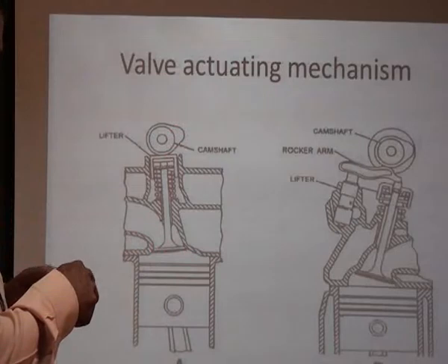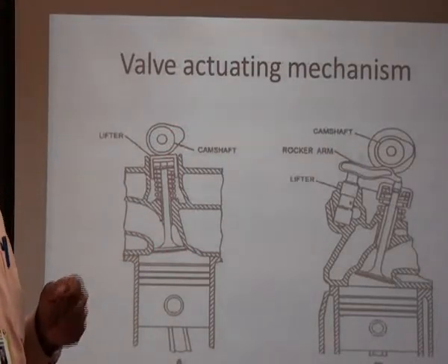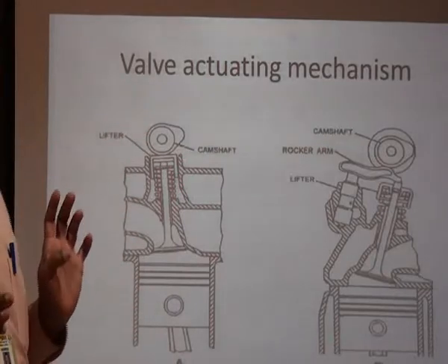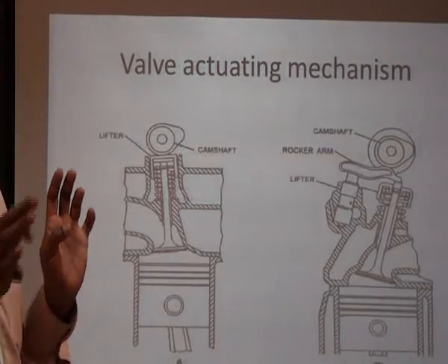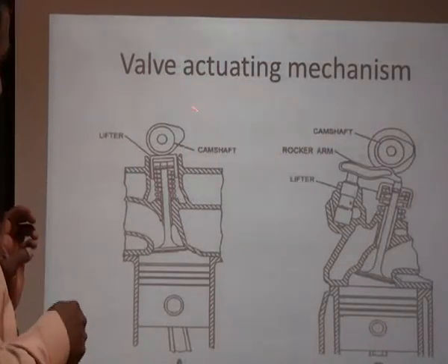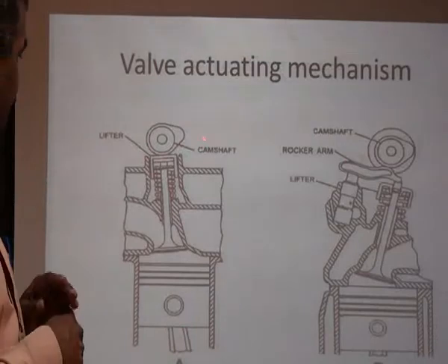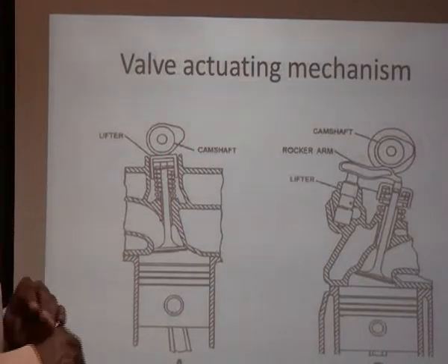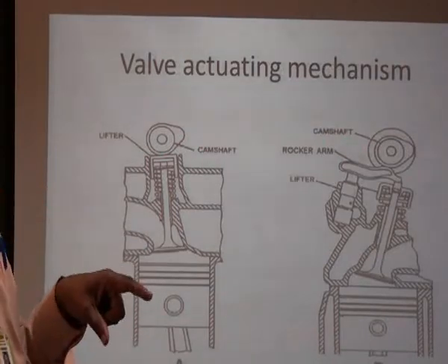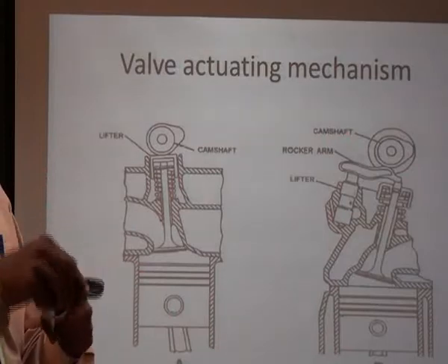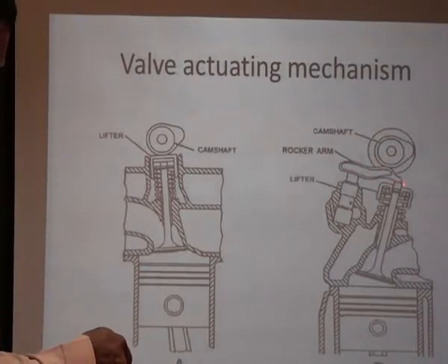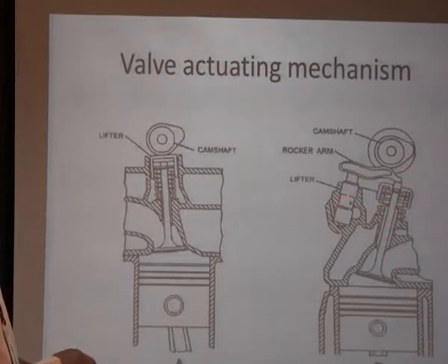When this bump portion crosses that area, again this spring takes into action and it closes the valve. It's a very simple mechanism, but somewhat efficient. Only at the time when this bump comes here, then only the valve opens. Here is another set of arrangement with rocker arm. I told you it is like a rocker arm, up and down motion. Here it is the rocker, and the rocker is pushing down against the load of the spring. This we call as lifter.